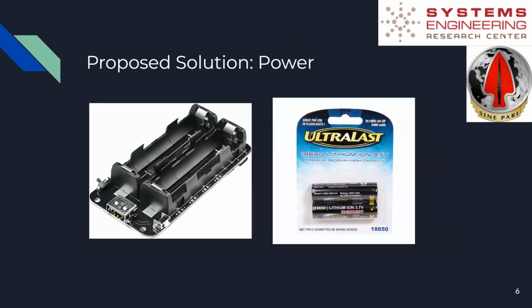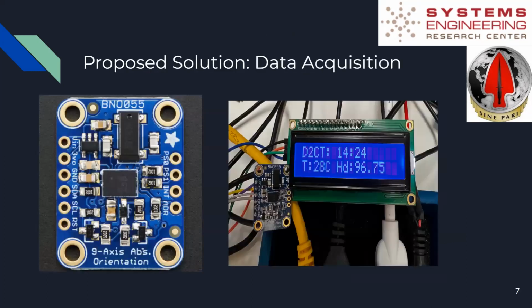Going to how we powered the board, we designed a solution using the 3.7 volt 18650 lithium ion rechargeable batteries. These fit into a device that boosted the voltage up to the 5 volts that we needed and provided power for 2.5 hours to our device.